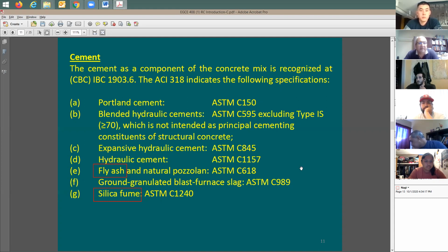Yeah, so what is the problem with the cement? Why don't we like the cement and just use it? Why are we using this fly ash or silica fume? Cracking. To fill in the cracks. Yeah, because cement is a high shrink material. Shrinkage is high. When the cement is shrinking, you're going to see lots of cracks. The good thing about fly ash and silica fume is they don't shrink that much. Lower shrinkage material, so you'd like to use it. It reduces the amount of shrinkage and the hair cracks that you're going to see on the surface of the concrete. And they're cheaper.